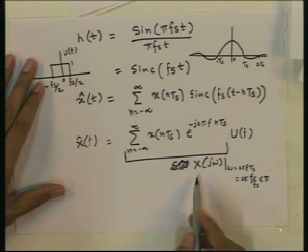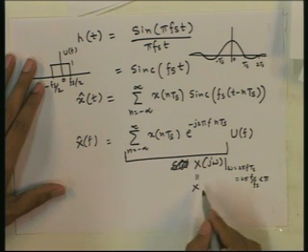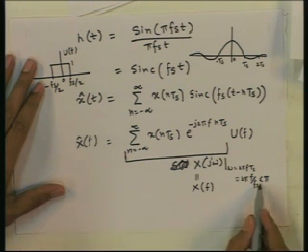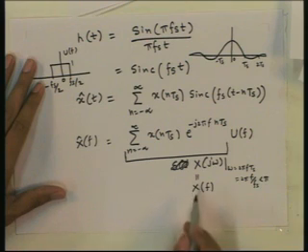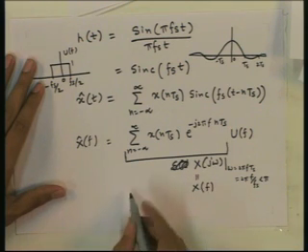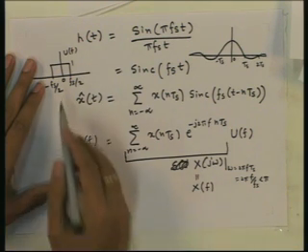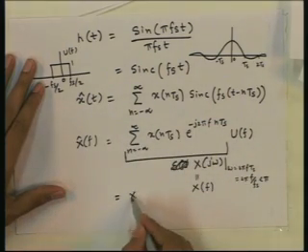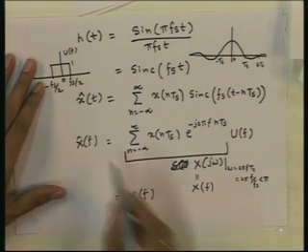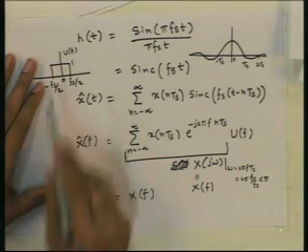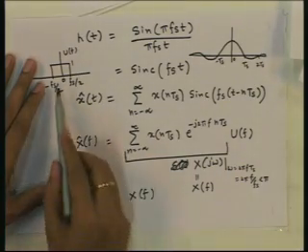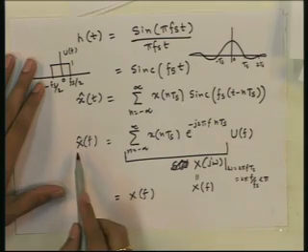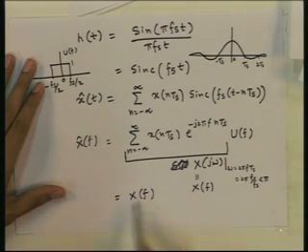So in the minus pi to pi range, this is the DTFT, and this DTFT is the same as the Fourier transform of the original signal, that is X f, if f is less than Fs by 2. For f less than Fs by 2, we get this, and when we multiply this by U f, we get the same thing X f, because f is in this range.